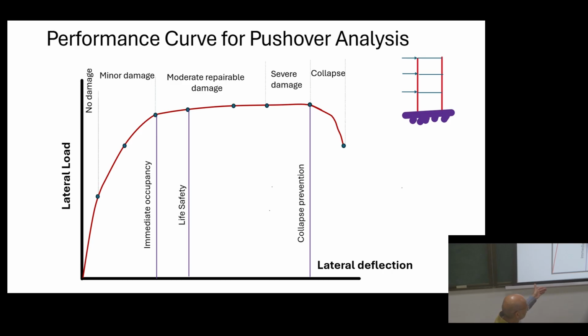If you force deformation of the entire structure, this is what pushover analysis is. You push it, so this is static, it's not dynamic. It's an equivalent system. Professor Datta showed yesterday a building they push, this is precisely pushing. There is an actuator, and how much you can push depends upon the actuator. The stroke is around 50 mm.